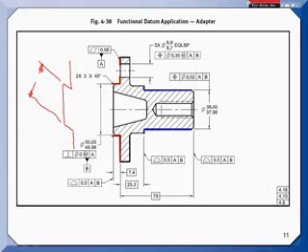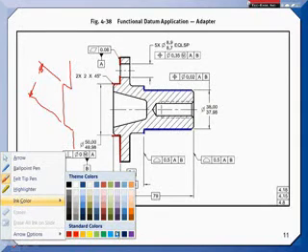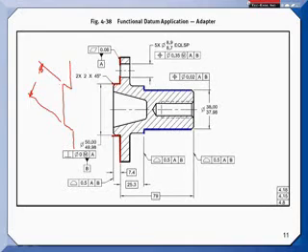Okay, now, if you go from the actual part and look at all of the other features that are positioned to datums A and B, with A being primary, B cannot be on that skewed axis. Am I correct? No, you're absolutely right. Let me change colors here. When I close in on B, I have to use a related actual mating envelope, which is the new term in the standard.